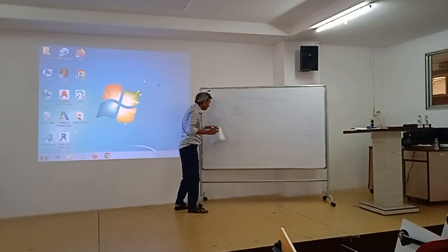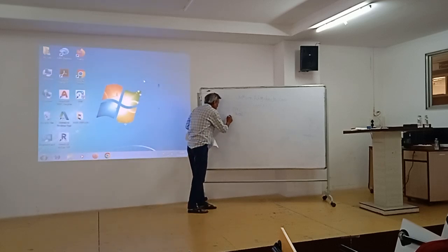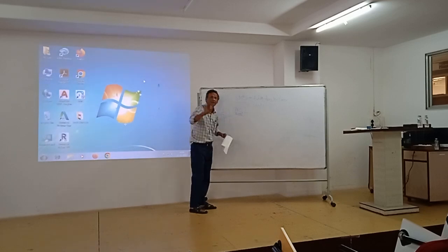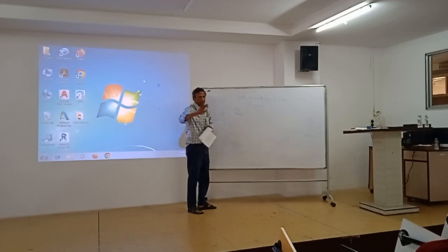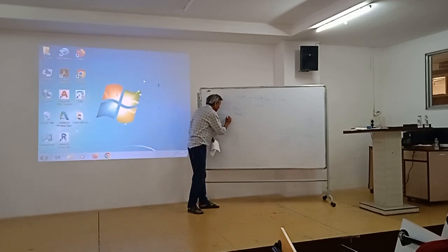Very importantly, you have not put any capacitor. Some small capacitor may be there, but it is a filter capacitor. It is not a large capacitor, which we usually show like an electrolytic, polarized capacitor. So it will be a small value capacitor.